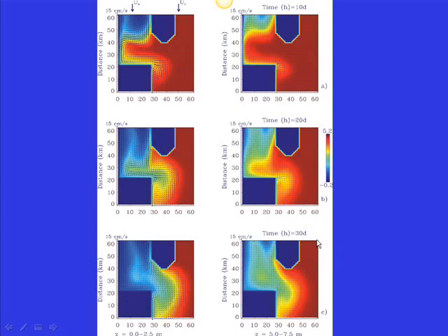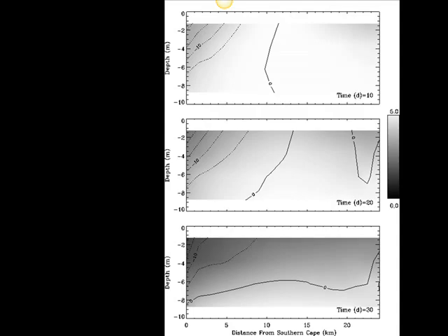Okay, so the reason I show this example is because we want to see how close to geostrophic balance the exchange flow is. If I look at a transect right at the mouth, I can see the exchange flow and see how close to geostrophic balance it is. How would you determine how close to geostrophic balance it is? Obviously by using the Margules relationship that we just saw. So let's see if we can do that.